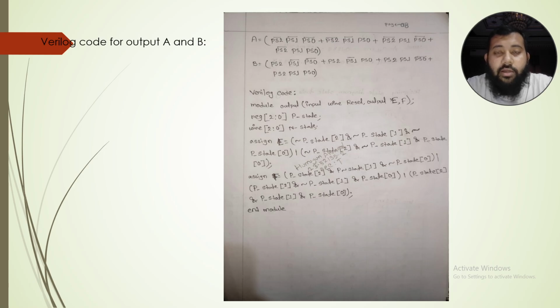And then the Verilog code, where we write the table. To implement the FSM practically, I wrote Verilog HDL code that produces the output signal for the blinking pattern. The module takes clock and reset as input and provides an output signal that alternates between high and low.